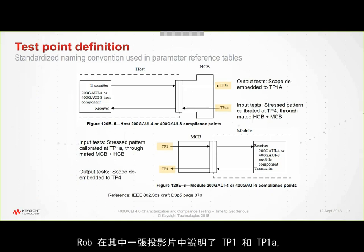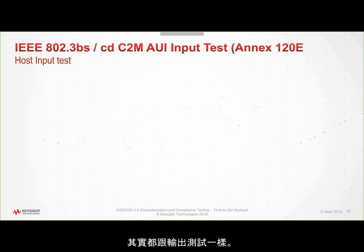Okay, and in one of Rob's slides, he was showing the TP1 and TP1A, and these are the designators that they use quite a bit in the standard. And in the beginning, they have this table, regardless of whether InfiniBand or OIF or Ethernet, you see the same illustration in all of them. And until you have this memorized, you might want to photocopy this page and just have it up on your desk because it just refers to where you are. So when you're doing the input tests, where do you put the signal and where do you do the calibration? And the same thing for the output tests.